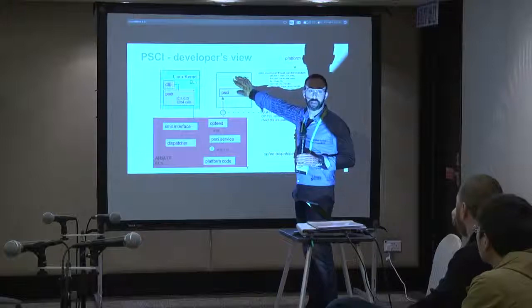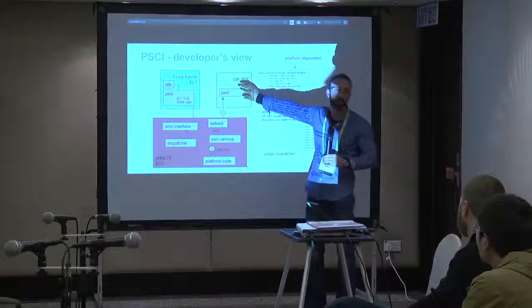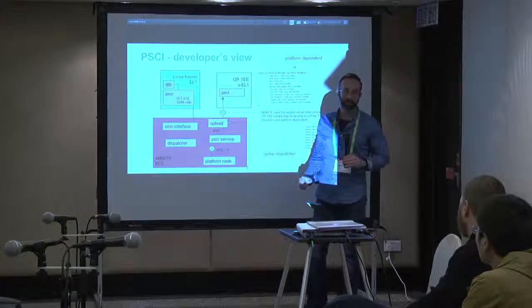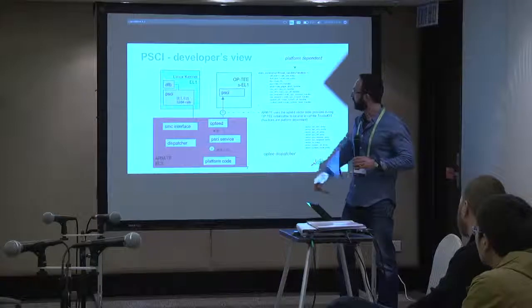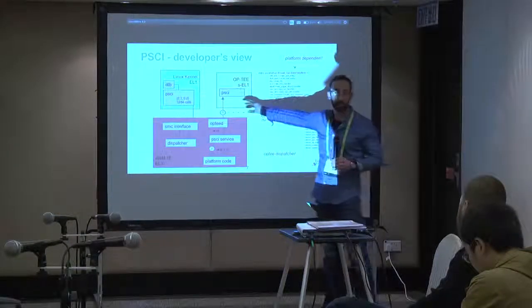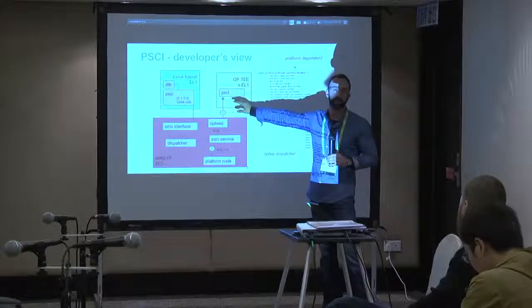This is typically not SMP aware. This is typically bound to a single core. And when you want to shut that core off, you need migration to migrate this out of the way, if the interface is supported. And today, OP-TEE cannot be moved.